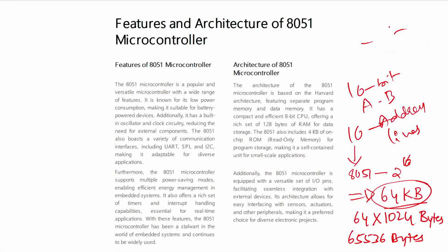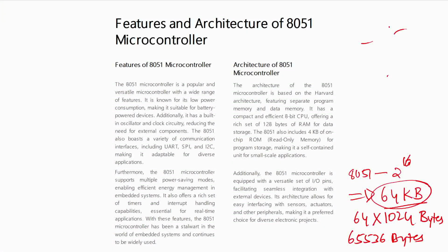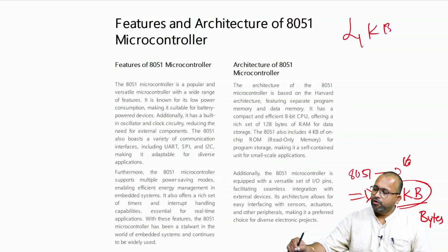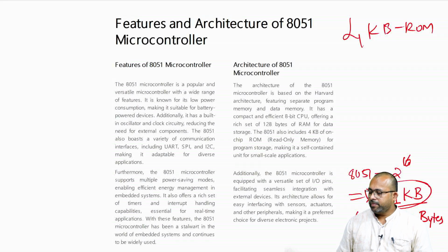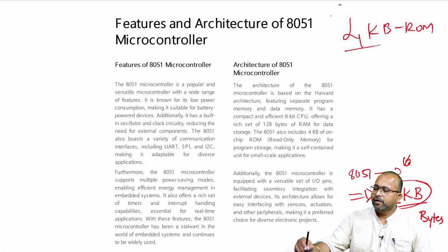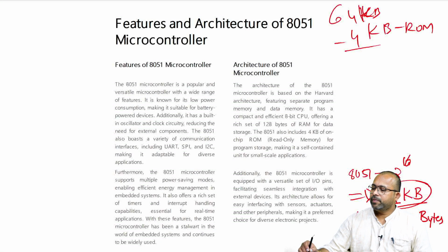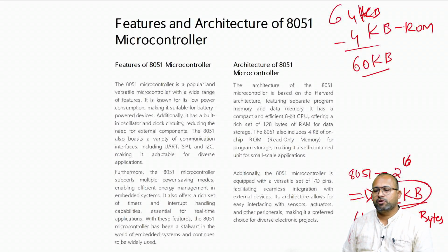But we discussed that the internal ROM is 4 kilobytes. Out of the 64 kilobytes maximum memory, 4 kilobytes is already present on the chip, and the maximum memory that we can interface externally is 60 kilobytes.